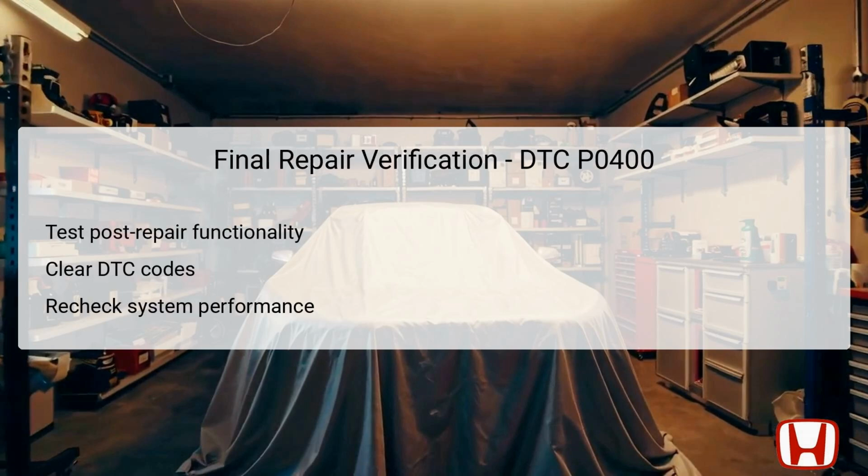Once repairs have been completed, a final verification is vital to ensure all systems are operating as they should. Start by testing the functionality of the EGR system post-repair to confirm that the leak has been successfully addressed. Clear any DTC codes using the HDS device and monitor for any immediate reoccurrences of the P0400 code.